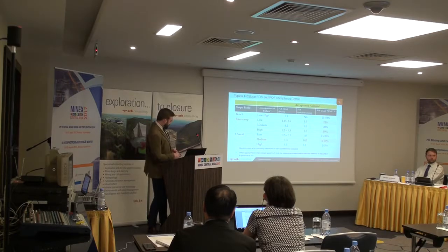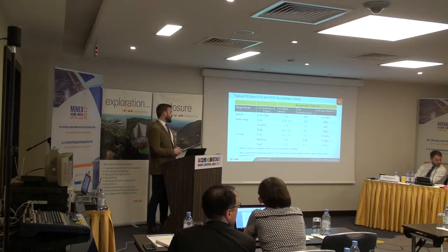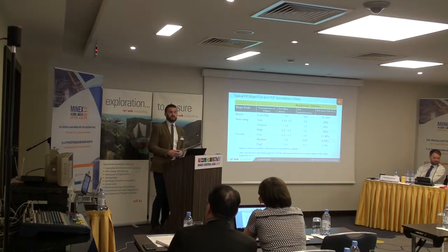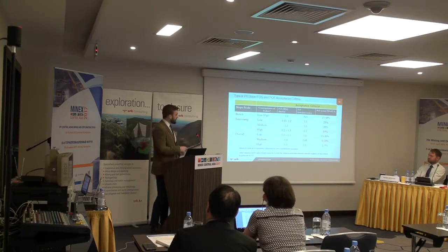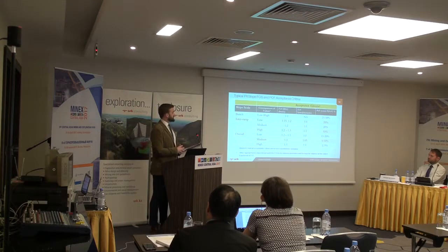I want to bring your attention to these bullet points. Here I've labelled that other approaches to slope design apply the factor of safety to the material parameters. That's based on something like a Eurocode design, where you apply your factors of safety to the material parameters.